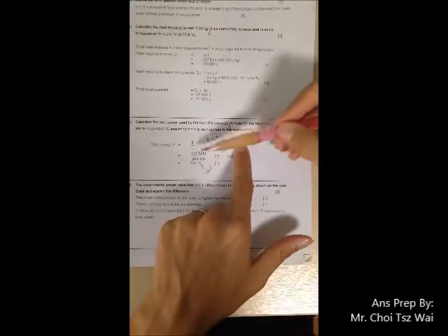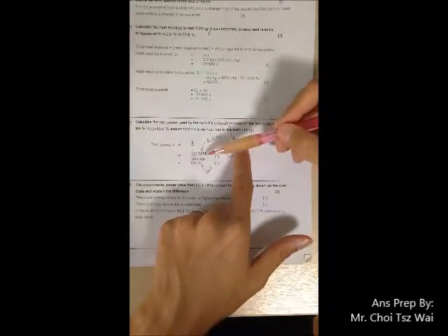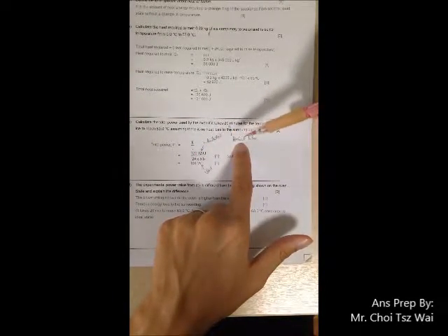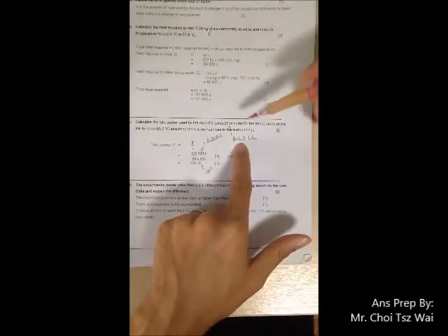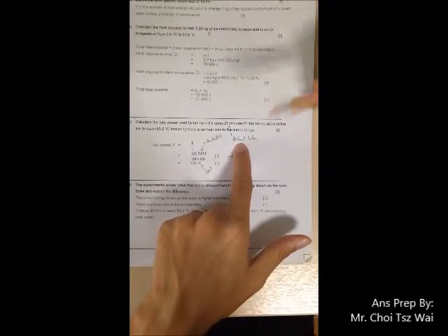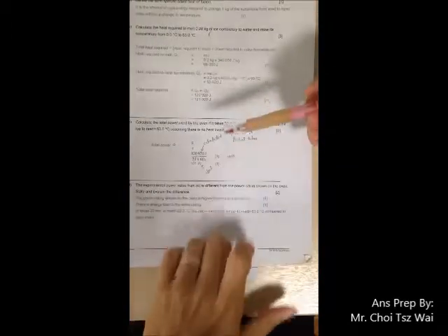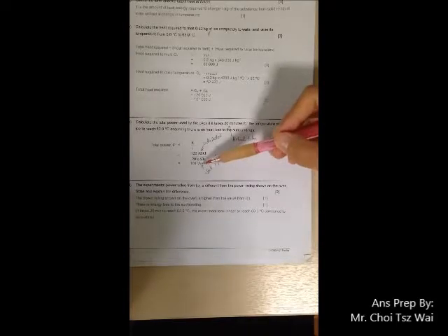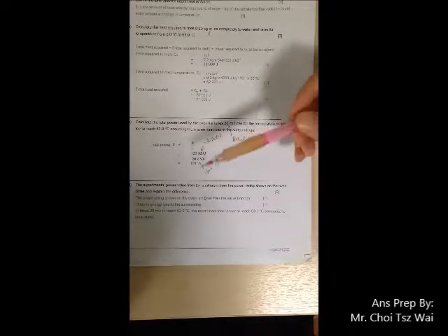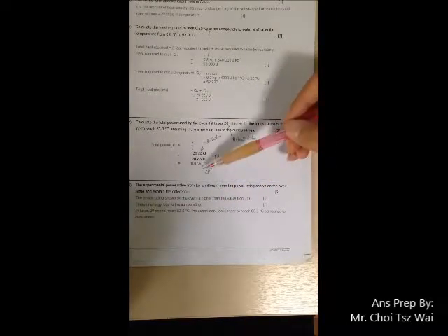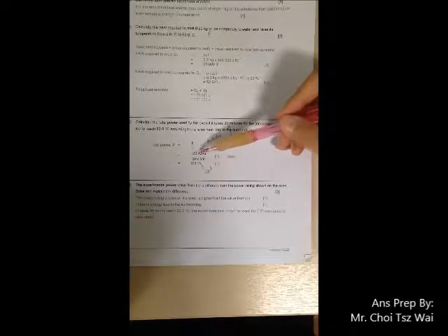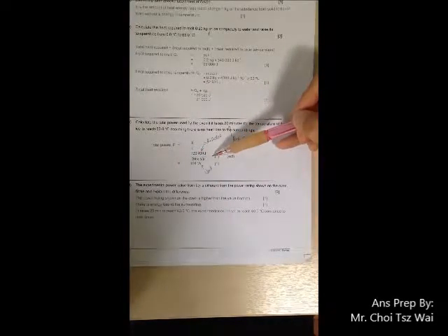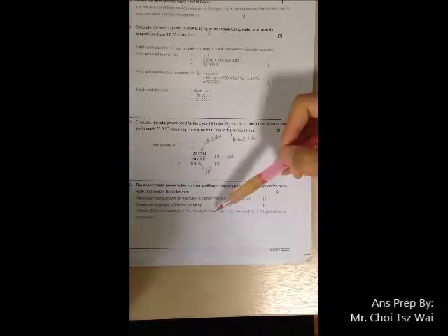If you just supply this amount of energy, you will definitely require more time to melt and then bring the ice to 63 degrees Celsius. So the power rating of the oven must be greater than your calculated value here. Okay, and that is because in the actual situation, you must supply more energy than this 120,920 joules. Okay, and that is how you explain this.